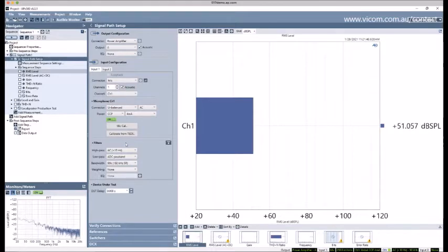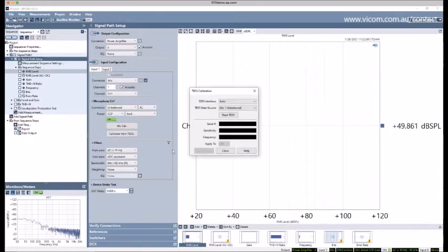And now I'll go ahead. I'm actually, like so many of us, working from home right now, and I'm remote controlling a system in our office. And so unfortunately, I'm not physically there to put an acoustic calibrator on the microphone. So instead, I'm going to take advantage of the fact that we can directly read the calibration data from the microphone via the TEDS, or Transducer Electronic Data Sheet system. So that reads that out directly. The last time this was calibrated, it had a sensitivity of 1.36 millivolts per Pascal. I'll go ahead and set that sensitivity.